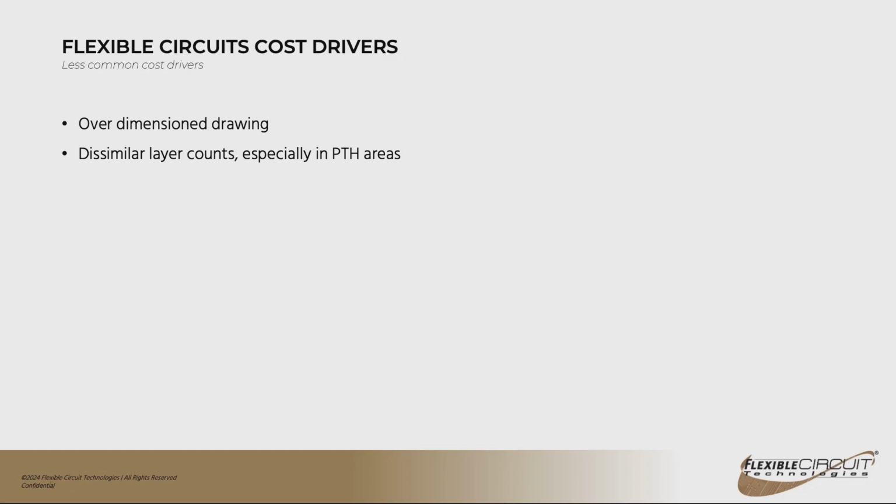You want to make sure that your layer count in each area that has plated through holes is exactly the same. Even if you're just putting pads on those layers, don't try and delete them, because it can be done, but it makes it very expensive. A lot of masking is required and a lot of hand operations in order to be able to manufacture that. So make sure that all of your plated through hole areas have the same layer count.